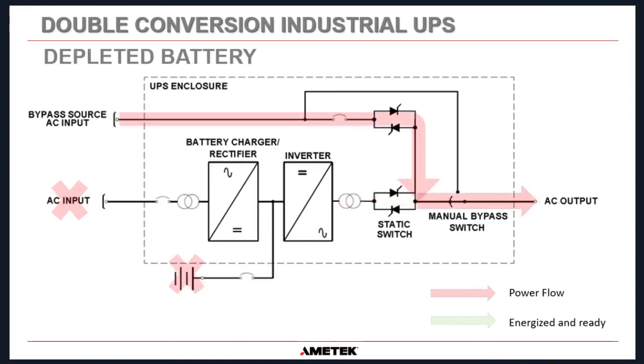And then in our systems, we have a circuit within the UPS that, once the battery gets down to 1.75 volts per cell, which is 105 volts DC for a 60 cell system, says we have to disconnect the batteries to protect them from being over discharged, because that's the worst thing that you can do to a battery, is discharge it too deeply and leave it discharged for a long period of time. It causes sulfation on the plates of the battery and seriously reduces the life of the battery. So we want to protect against that.